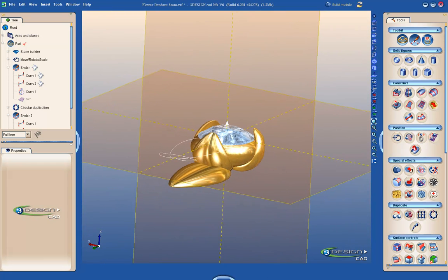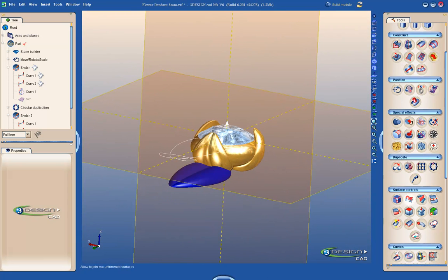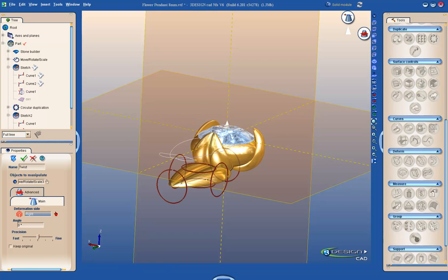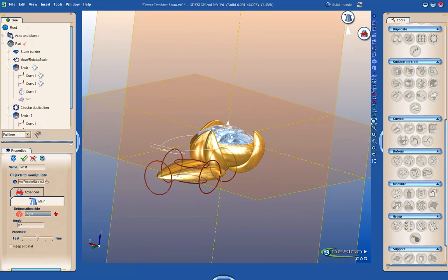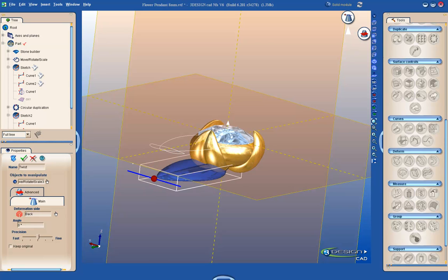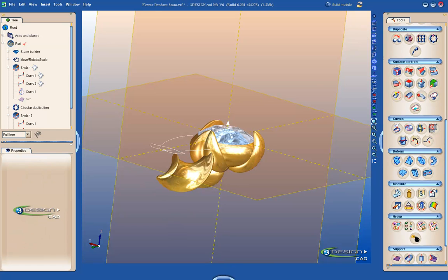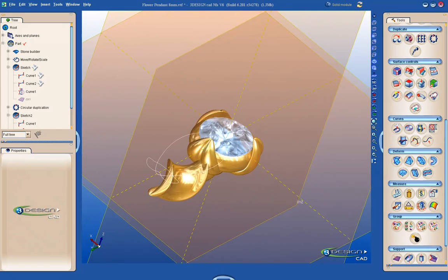And this one, we're going to twist before we bend. So we're going to click on it, and another deform tool is twist. Instead of getting the arrows, this time I get these circles, which are kind of like steering wheels, I guess. And I can twist it. I'll validate just so you can see the effect. And it keeps the piece solid.